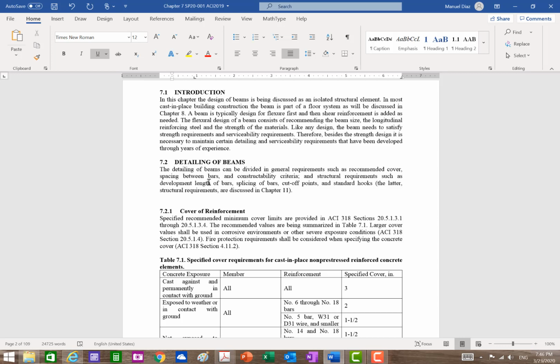But it has aggregates, it has sand, it has all the liquid with those aggregates and all that has to flow through, right? So you put your bars too close, then some aggregate may be trapped in there, and it will not let the cement and all that go around it. So that's very important that you keep then a proper spacing of the bars.